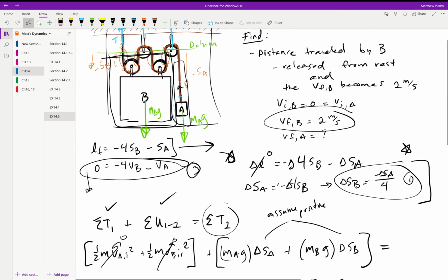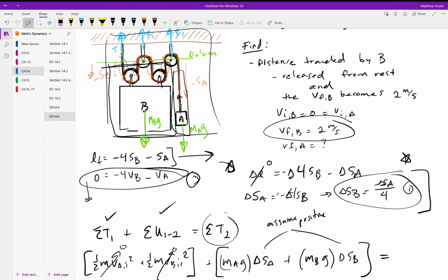The tension does do work on the mass A. So do the tensions on B, but not if we draw the box around the system, the whole system. Those reaction forces and tensions can be eliminated. It's called a single system. These forces are supports and they don't move while the blocks are displaced. The weights do positive work if we assume they both move downward, which we did.